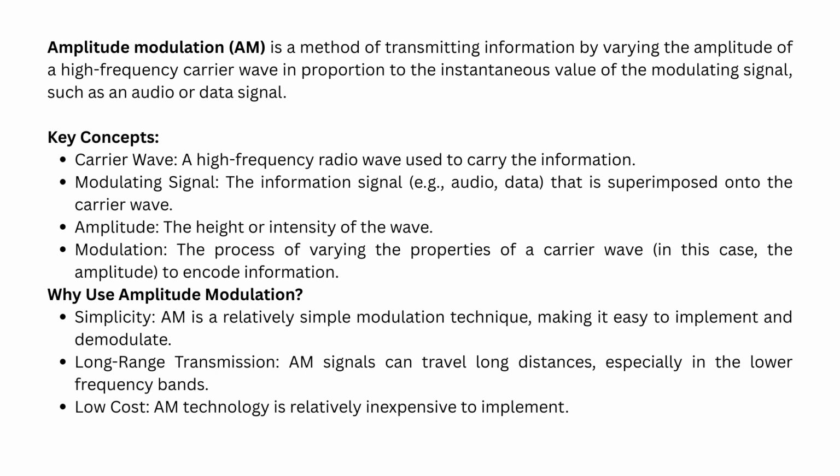Another advantage of it is long range. It can travel long distances, especially at night. And also it has effective bandwidth usage. That means it occupies less bandwidth, letting more stations share the spectrum. So that's a useful thing, and the efficient bandwidth usage reduces the cost. So these are some of the advantages of AM, amplitude modulation.